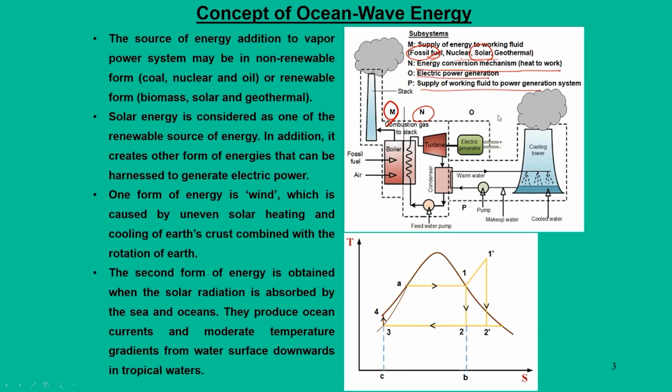Now, if you refer to these temperature entropy diagrams, for conventional fossil fuel based steam power systems, our working fluid was mainly water, and to get the advantage of water, we bring this water to the maximum possible heated locations, that is towards the superheated regions. Then only does the steam have maximum potential to be expanded in the steam turbines.